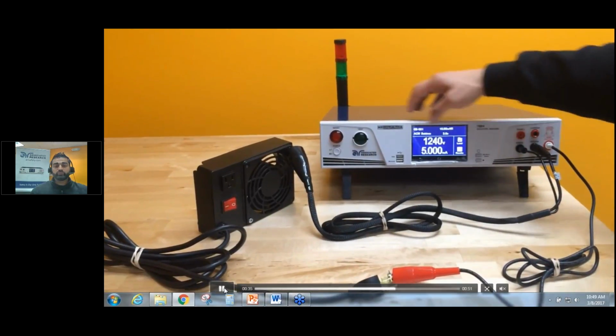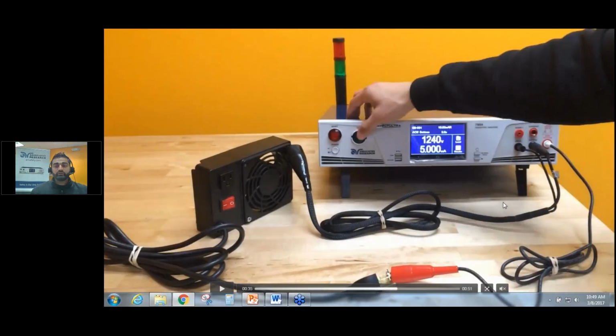So I'm going to pause it really quick before he presses test, and if you take a look down here, we have a high voltage cable coming from our tester. We are using a paper clip just to do a demo, and it's shorting line and neutral together. So you can see the high voltage is being applied to the line and neutral shorted together. I could have easily gone to the ground pin of the product for my return, but I decided to use the chassis point of the product, which was the metal screw on this fan. So if this was my DUT, or what I'm in charge of in my production, this fan would need to be tested for HIPOT, and this is how I would hook it up.